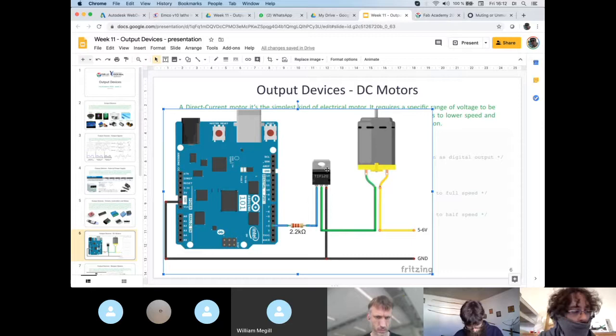Some of these devices can take a huge amount of amps, we are talking about hundreds of amps, only if they have proper cooling. If you have ever opened a power supply from a PC, for example, you will see giant heatsinks inside. This hole here, you attach a screw, you screw it to a giant heatsink.